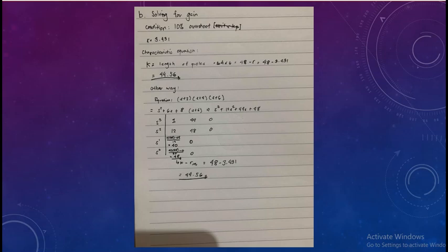Meanwhile, the other method utilizes the characteristic equation, which is solved by multiplying all the roots. The equation of roots is (s + 2)(s + 4)(s + 6). As we multiply those three, we get s cubed + 12s squared + 44s + 48.